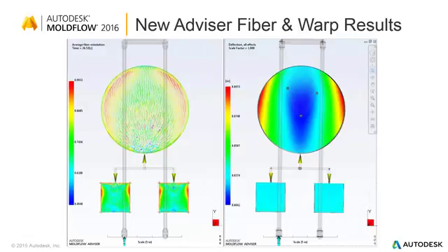Now we will show you the amount of warpage that occurs in the part, where in the past you'd have to look at how much shrinkage would occur between certain points and derive whether or not that's within tolerance. That's still possible, the old workflows are still possible, but we now also have the ability to explicitly show the amount of warpage that we predict, just like you have in the Insight product line.